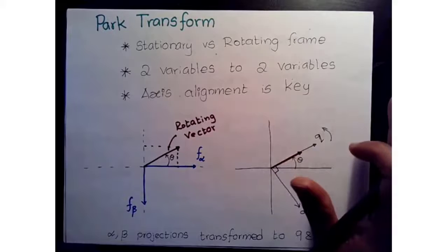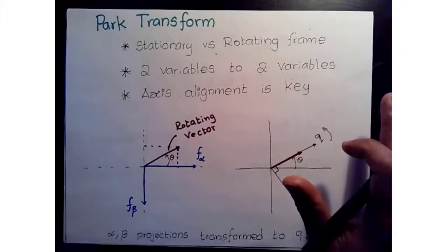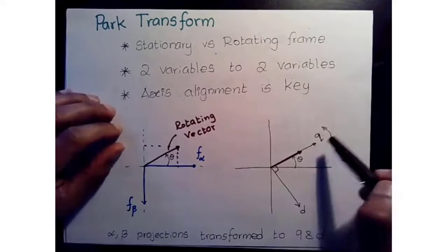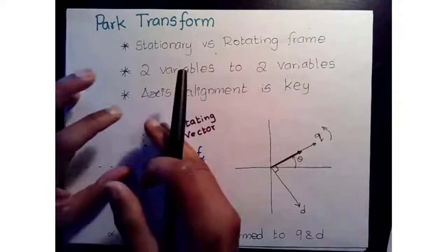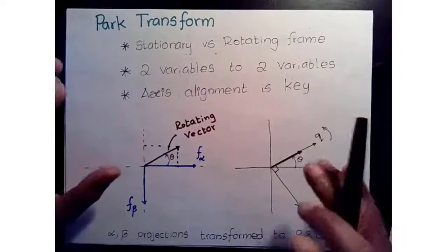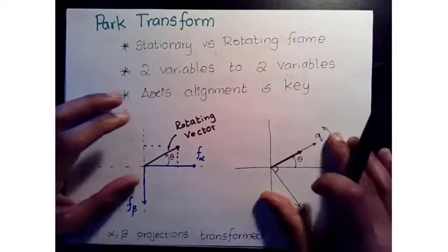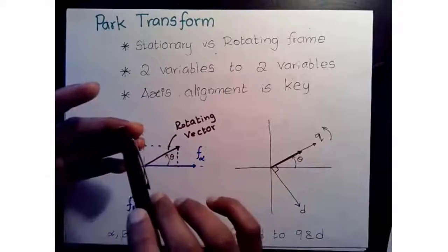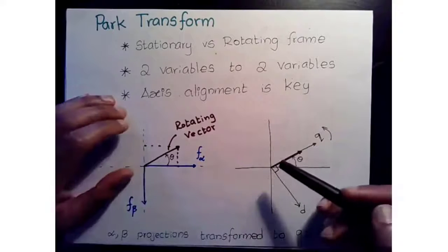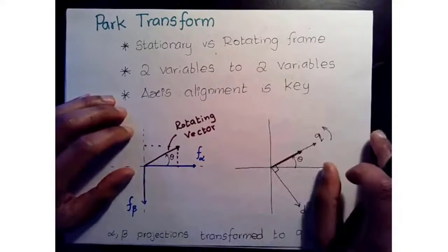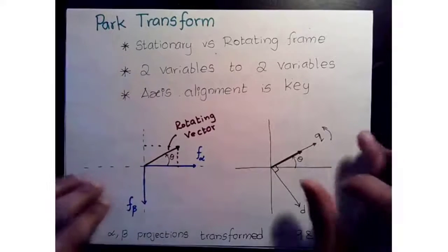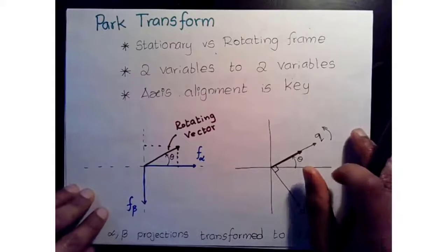All right. So now we need to be very careful when we specify where we are attaching our frames. Typically, we tend to bring all the variables to one frame. If we take the stator currents to the rotor reference frame, we will take the motor parameters to the rotor reference frame as well as our flux linkages, the permanent magnet flux, all that gets transformed. Otherwise, it will not be very straightforward. It'll be like a mix of variables and it's not easy to understand.